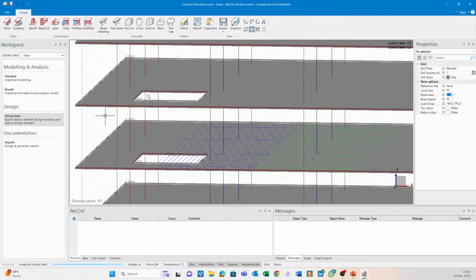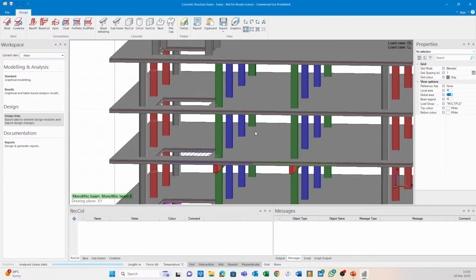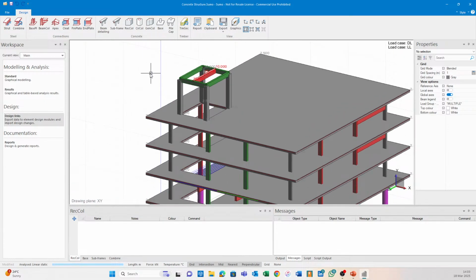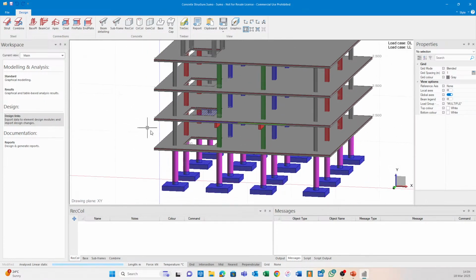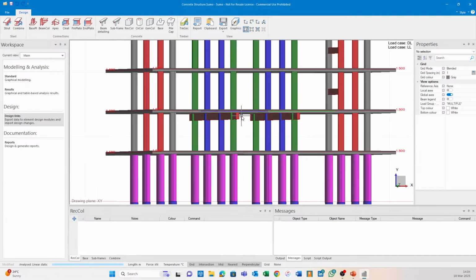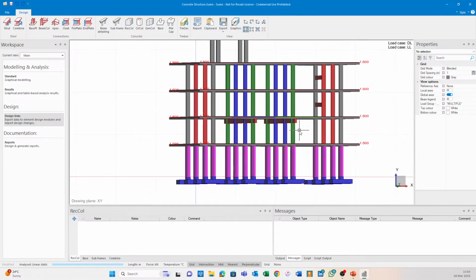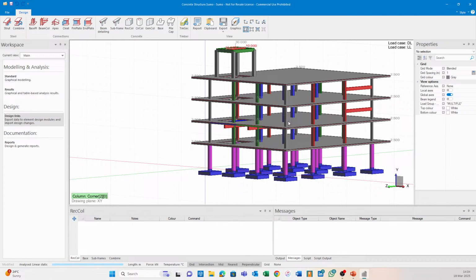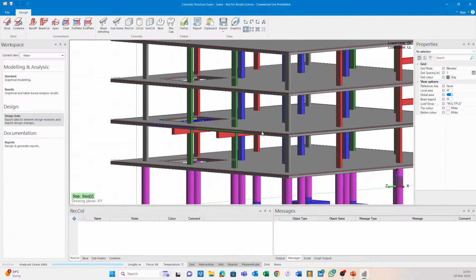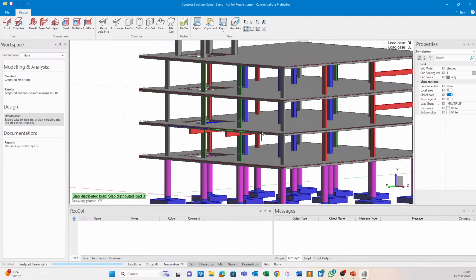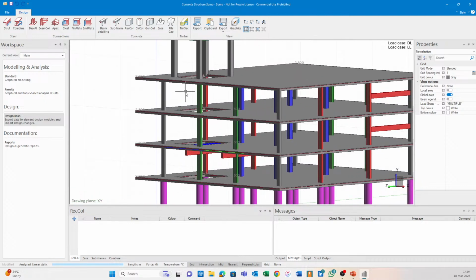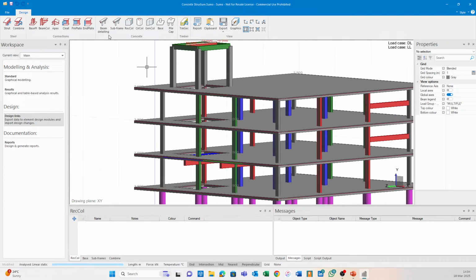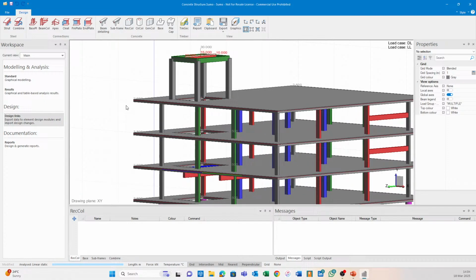So right, our first design link is beam detailing. Oftentimes there is a bit of difficulty with the beam detailing design link because we try to use it to design monolithic beams. Now, in general, the beam detailing design link is not best suited for the design of monolithic beams. It's not impossible, it's not taboo per se, but it isn't specifically what the beam detailing design link is suited for. We'll get to subframe strips after this.